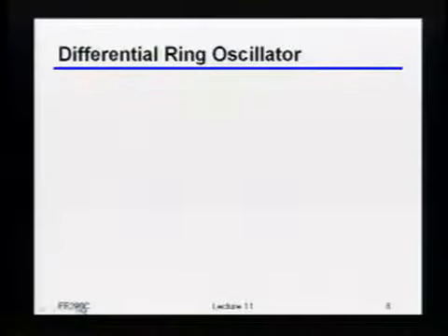So there's lots of different reasons why you might want to do this. One is just getting the differential phases like we just talked about. But even independent of that, sometimes you'll want something like a multi-stage differential ring. As an example, another fairly common technique is to run the link at what's called double data rate, meaning that on both the rising edge and the falling edge of the clock, you try and grab data, right?